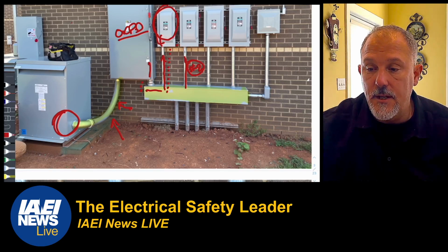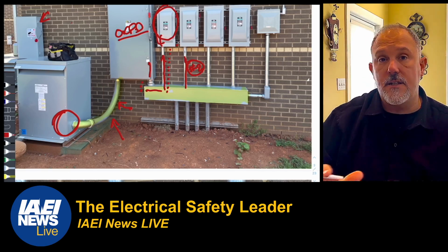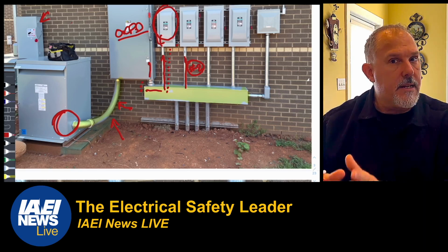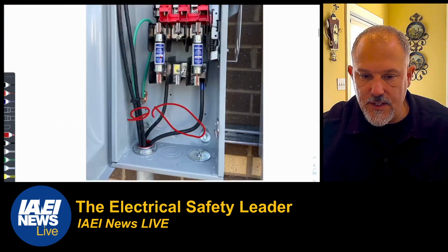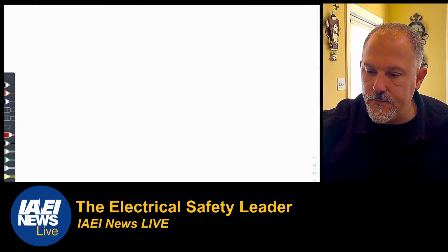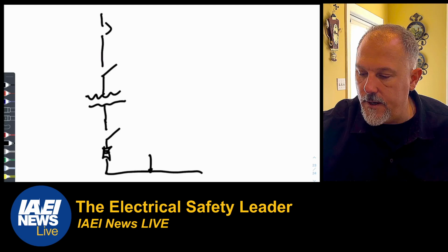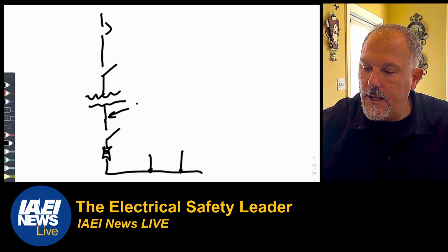And if you think about how we size, and remember, that's just a disconnect switch, there's no fuse in there, but there's a circuit breaker that is feeding that switch. That disconnect is just there to help the electrical contractor, electricians establish an electrically safe work condition, right? To turn that transformer off for maintenance and other reasons. So that line side overcurrent protective device in the transformer, let's draw it out. What you've got there is a circuit breaker feeding a disconnect, feeding a transformer, which then goes to a fusible disconnect, and then to our taps, right? So this right here, that portion of the circuit, is our transformer secondary conductors.